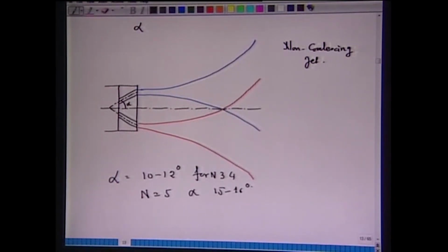From the refining point of view, the behavior of the jet is important. The behavior of the jet depends on the surrounding in the converter. As I have said, when the blow begins, the oxygen jet is surrounded by the hot atmosphere. As the blow continues, the surrounding of the jet changes.